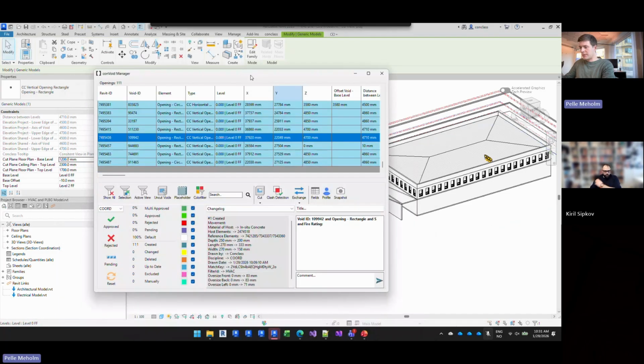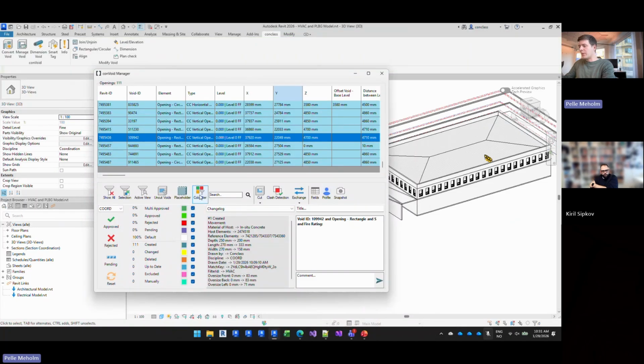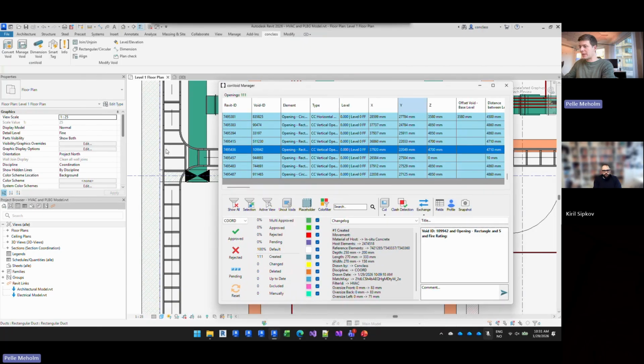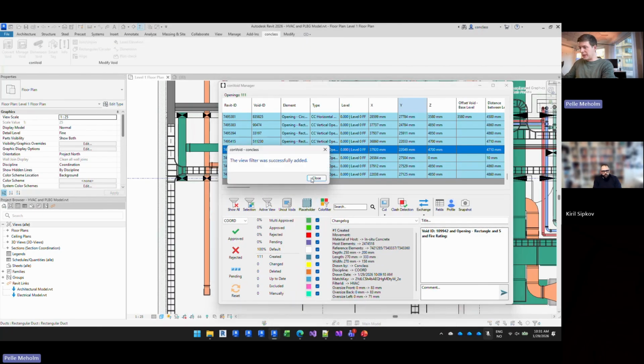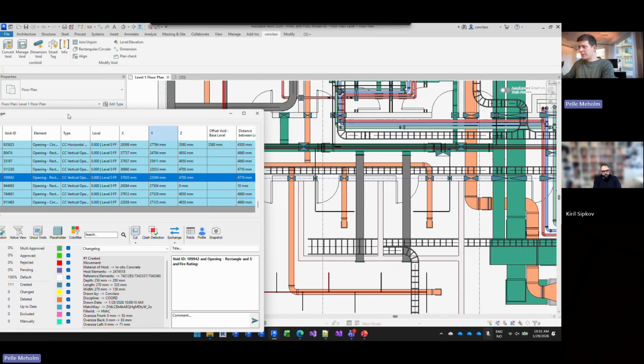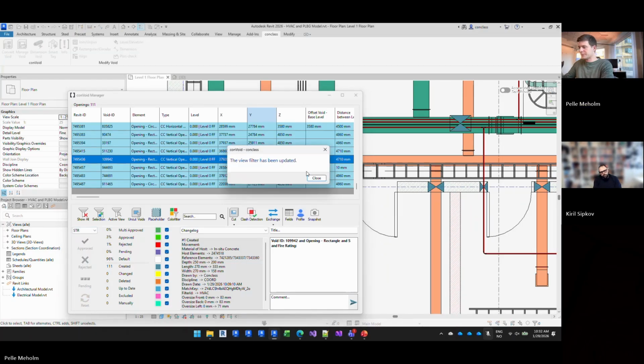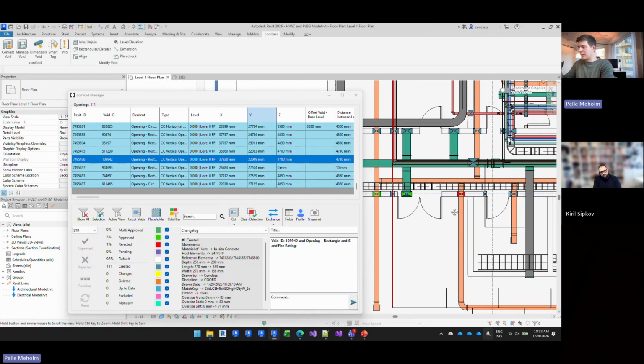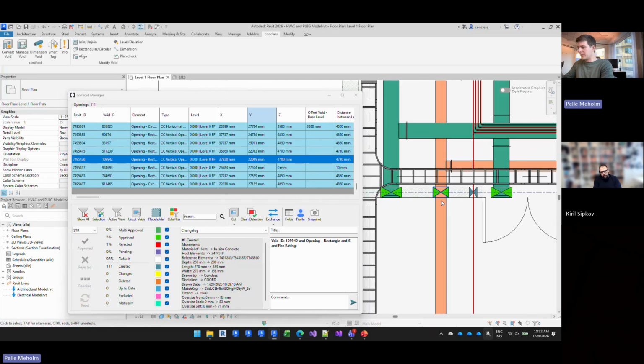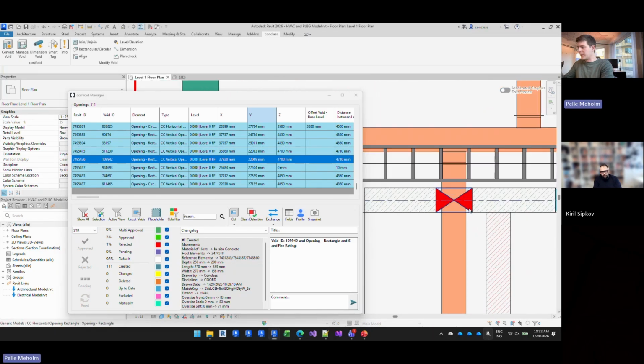Successfully imported. Great. Now I want to review the approvals. I will switch to 2D view and add a color filter to give me the highlighted status colors of the structural engineer. Currently I am the discipline coordination, so I will switch to the view of the structural engineer. I can already see that these ones are approved and this one is rejected.